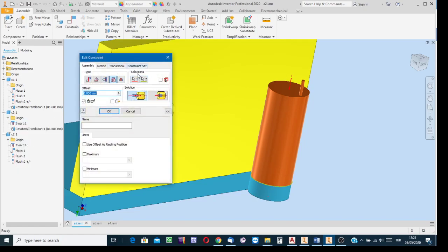Yes, I see from the dialog box, for positioning the brownish one with respect to the bearing part of the blue component, an insertion type constraint has been input. Clicking on this, we can position the longitudinal axis in alignment or at a certain distance with respect to the other. Here the offset value is 0. This means the axes are in alignment.